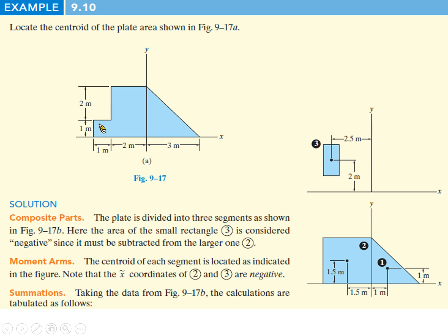First of all, we can add one more area here. Okay, you can see on the right hand side we have cross section area 3. So we make it become a full area and do the calculation. And then later on, we use a superposition concept. We just cancel the effect coming from this area, and then we can work out our solution.